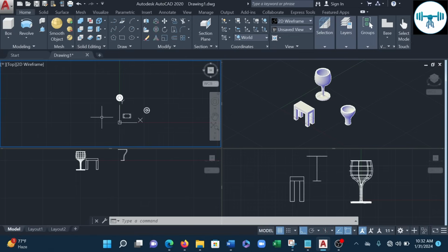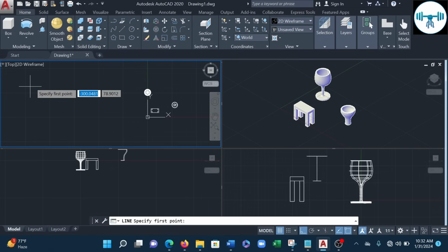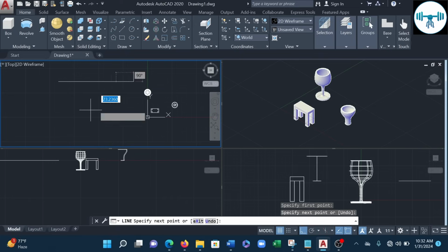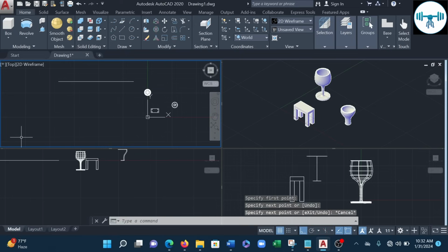They are very, very important. So when you want to sweep, you must draw a path, which is the length of the pipe, and then you must draw a profile, which is the cross section. Since we said we just want to use a very simple straight pipe, the path of this pipe is just going to be a straight line. So I'll just draw a straight line. We are not keen on dimensions this time around. That's the length of the pipe.